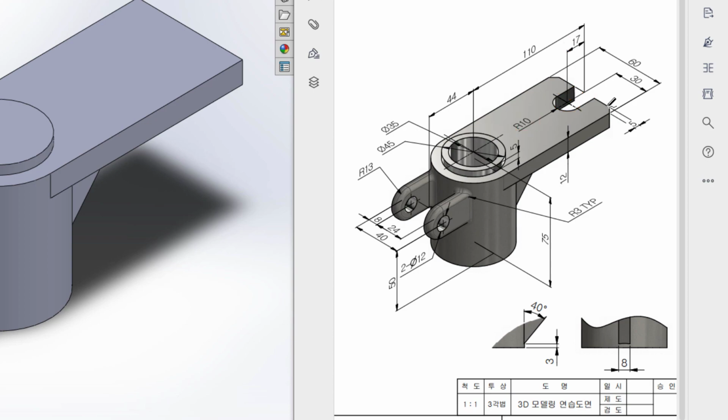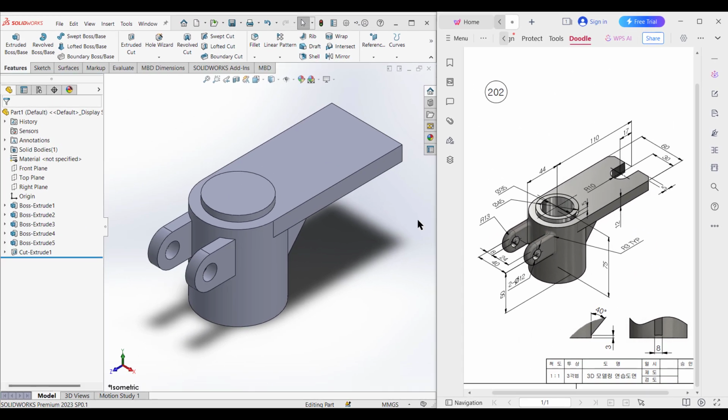After that, we can see we have a chamfer of 5 unit here and another chamfer of 5 unit here. So we'll do a chamfer. Okay, so let's go back to our sketch, and before that we can see we have a fillet here and here, and all the fillets are the same, so it will be radius 3 fillet. Okay, let's go back to our model.